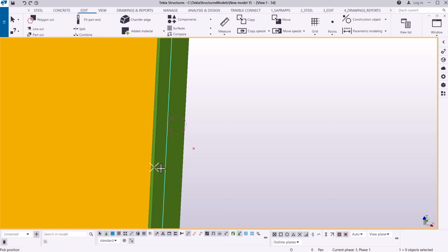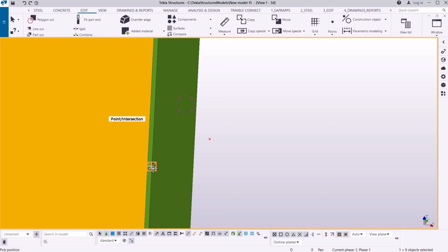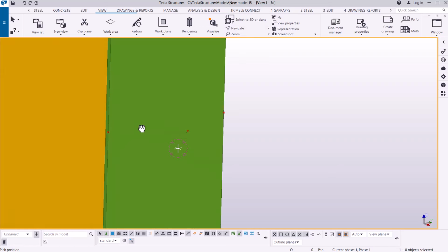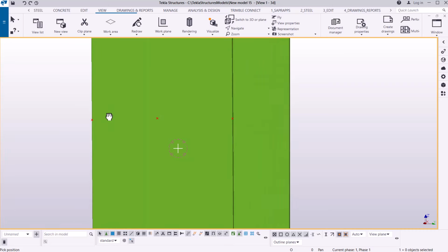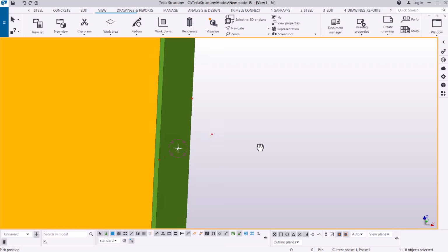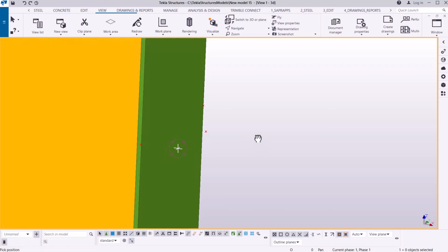Then once I've moused here and I've clicked a point here, now I'll go to the other end and try to start seeking a point that will be perpendicular to this point here. So I just mouse at the edge of that, then click. So to confirm that, I'll come to view once again, or you can just press Ctrl R and pick your rotation point by left clicking, then you'll be able to rotate like this. So if I turn that round, you'll be able to see the point is actually right in the middle, but the middle one is actually out of place between the two.